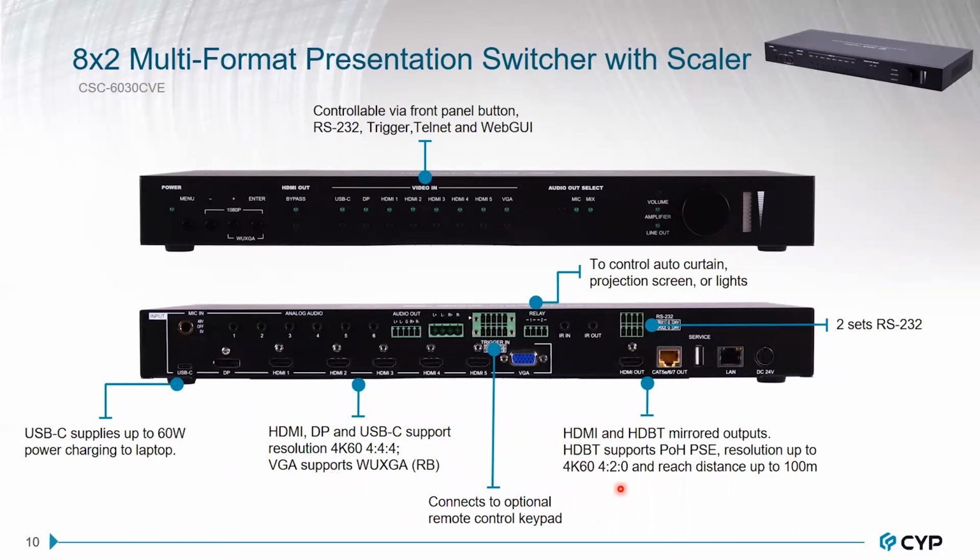The HDMI and HDBaseT are mirror outputs. HDBaseT output supports PoH PSE, resolution up to 4K 60 4:2:0, and the maximum reach distance is up to 100 meters.